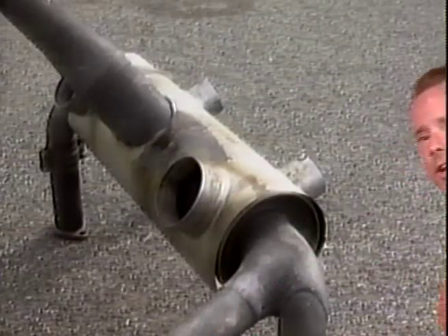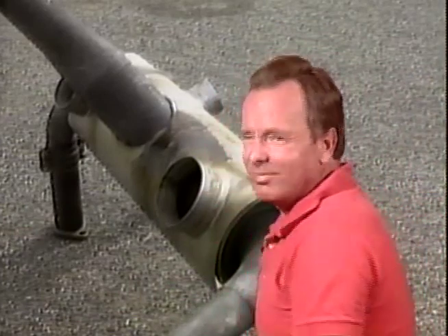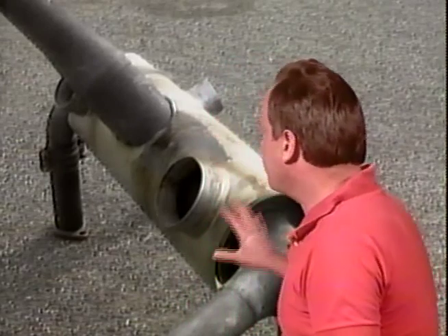So as a mechanic, what are you going to do about all this? Well, you're going to inspect the exhaust system. That's what you're going to do. Let's talk about the way they're going to ask you questions about this on the FAA written exam. Here's one. The exhaust system on aircraft using a jacket around the engine exhaust as a source of heat should be visually inspected frequently. And operational carbon monoxide detection tests should be performed periodically. They're saying check for carbon monoxide gas inside the cockpit.